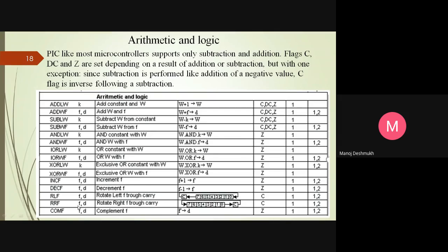No, it is not there. It is a type of reduced instruction set, so instructions are reduced. We have to go with the carry only. And if you do not want to modify the contents, then you have to keep the status of the carry flag before using the rotate operation. Like if initially it is set and you want that particular bit to be 0, in that case you should clear the carry flag and then use this rotate instruction.